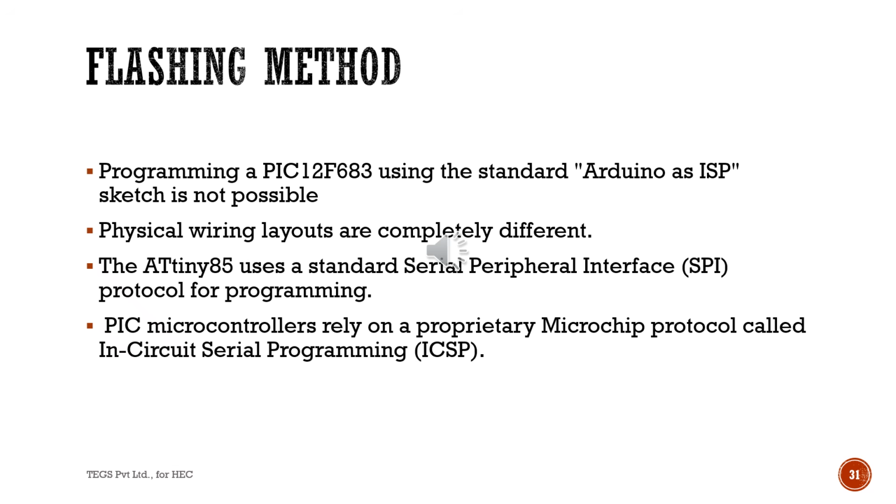Programming the PIC 12F683 using the standard Arduino as ISP sketch is not possible. The physical wiring layout is completely different. The ATtiny85 uses the standard serial peripheral interface protocol for programming. PIC microcontrollers rely on a proprietary Microchip protocol called in-circuit serial programming (ICSP).